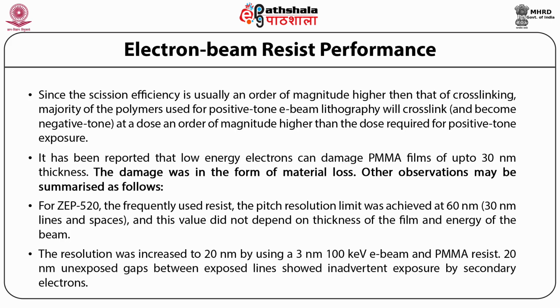Secondly, if the resolution was increased to 20 nanometer by using a 3 nanometer 100 kilo electron volt E-beam and PMMA resist, 20 nanometer unexposed gaps between exposed lines showed inadvertent exposure by secondary electrons.